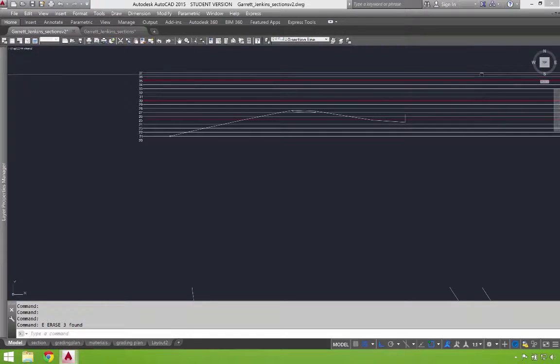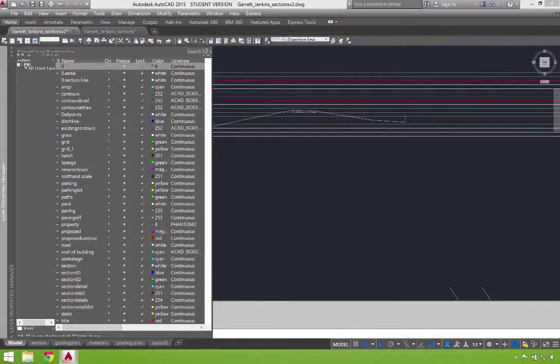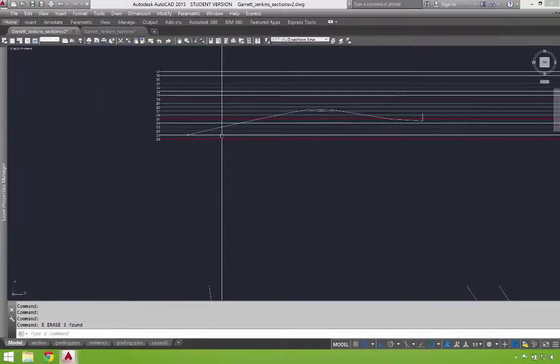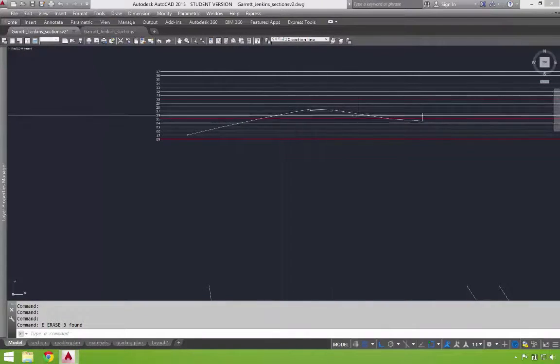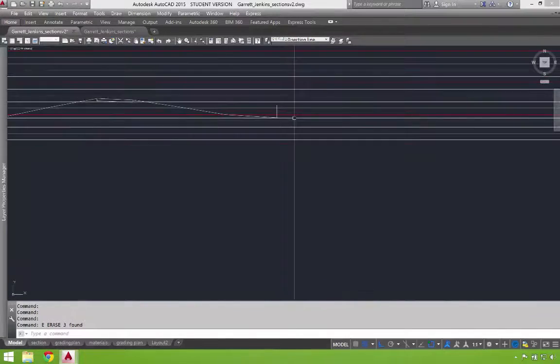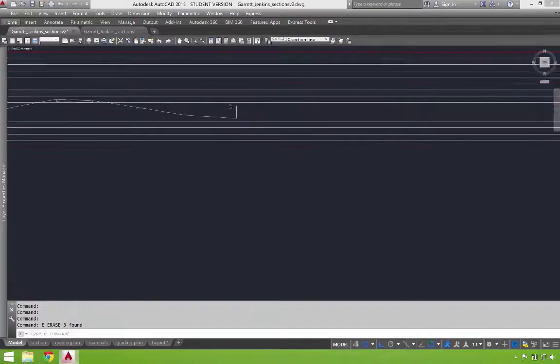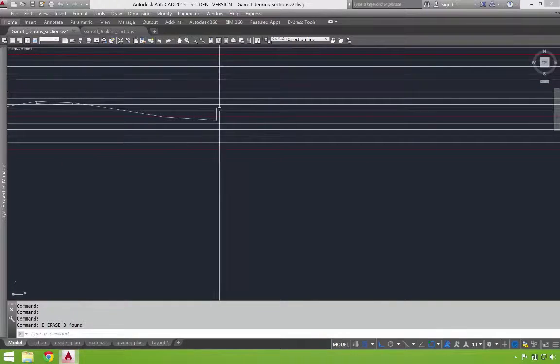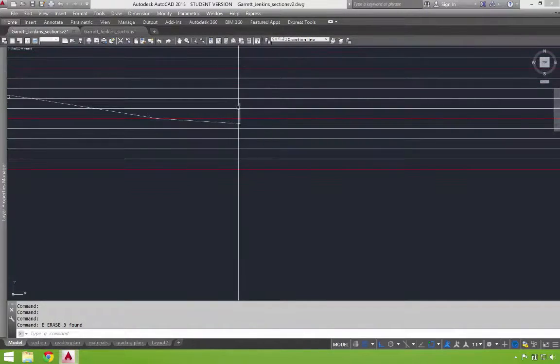Now, when creating the section line for terrain, it's fairly easy. You pull the contours where they cross the section line straight up and sort of connect from point to point and can get the terrain. Now, for more subtle things like this stage in this case, where we have slight slopes that actually don't cross a contour line, it becomes a little more difficult. Right? We can do it a couple different ways.